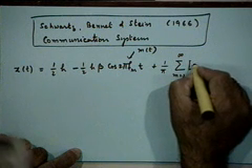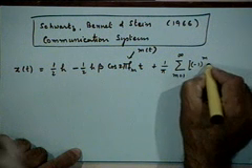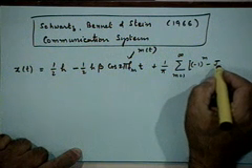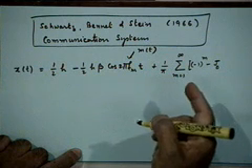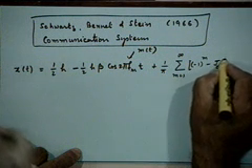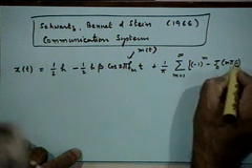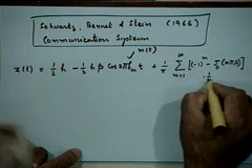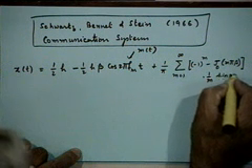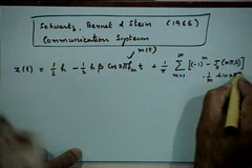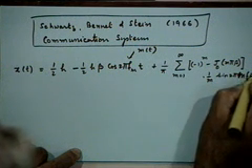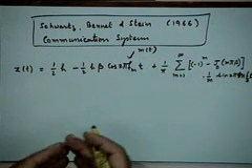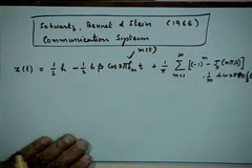The mth coefficient is minus 1 to the power m, and very surprisingly or not so surprisingly, the Bessel functions appear again, just like when we went from AM to FM. J0 of m pi beta, into 1 by m sine of 2 pi m fs t. fs is the sampling rate of the pulses.